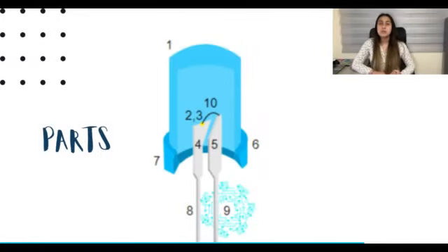Parts. 1. Epoxy resin encapsulation. 2. Semiconductor light emitting diode. 3. Reflector cup or reflecting cavity. 4. Anvil. 5. Post. 6. Base. 7. Flat base, identifies the negative terminal. 8. Connection terminal negative. 9. Connection terminal positive. 10. Connecting wire or whisker.